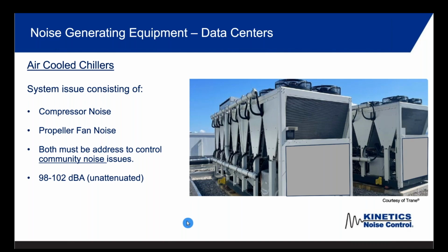I think it's very important when it comes to noise control: you have to know how the equipment operates. Noise control is kind of secondhand, because the key with any of these pieces of equipment is that they need to operate. Warranties cannot be voided. Air passage, cooling, everything needs to operate as it was designed to operate. So it's very important that anybody who tries to design noise control solutions knows how the equipment operates.